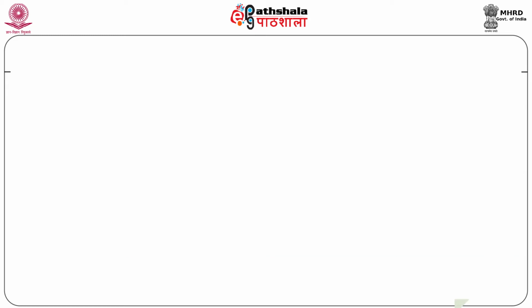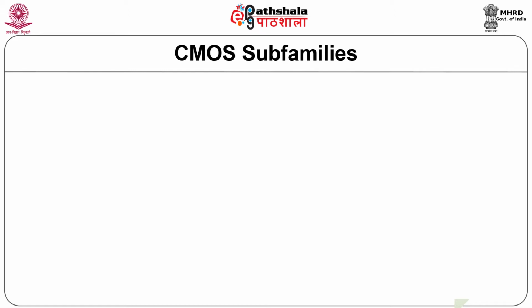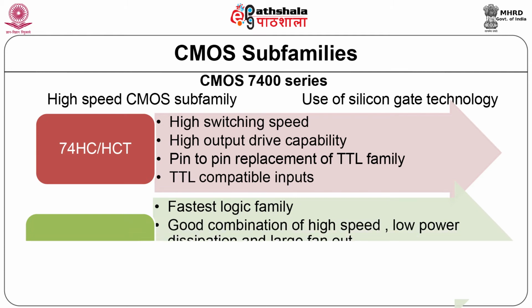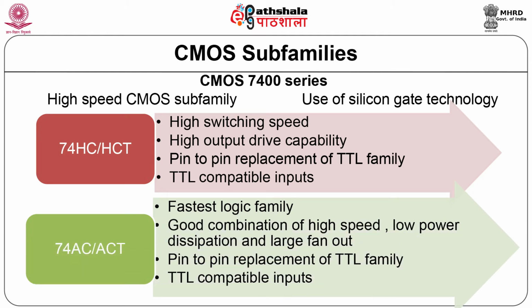Let us consider another CMOS subfamily, that is CMOS 7400 series. It is referred to as 74C series. The 74C CMOS subfamily offers pin-to-pin replacement of the 74 series TTL logic functions. For instance, if we consider 7400 as a quad 2 input NAND in standard TTL, then 74C00 is a quad 2 input NAND with the same pin connections in CMOS.